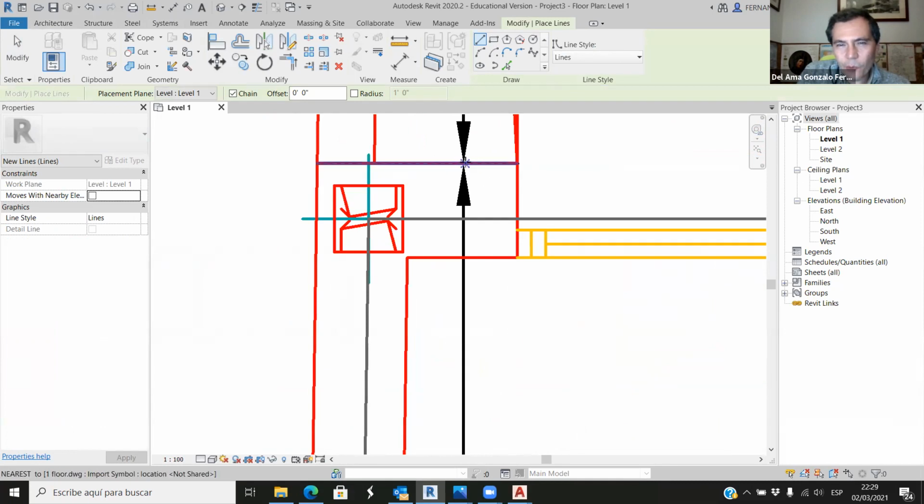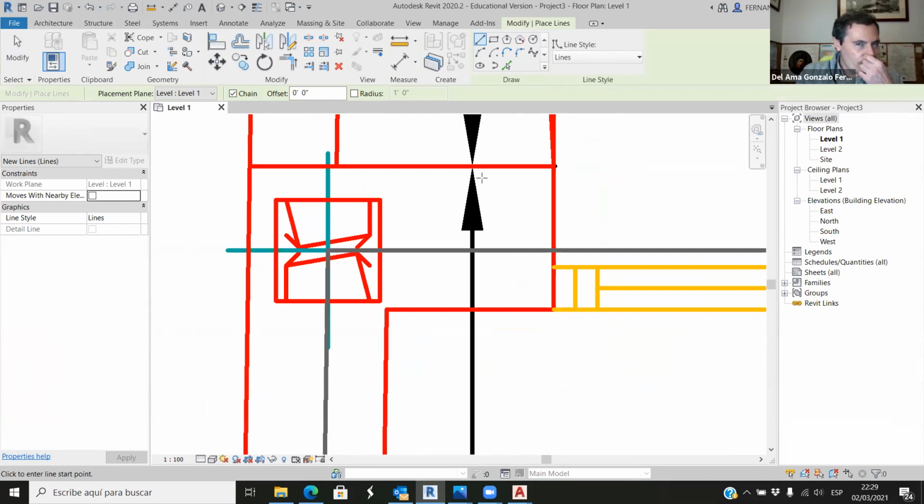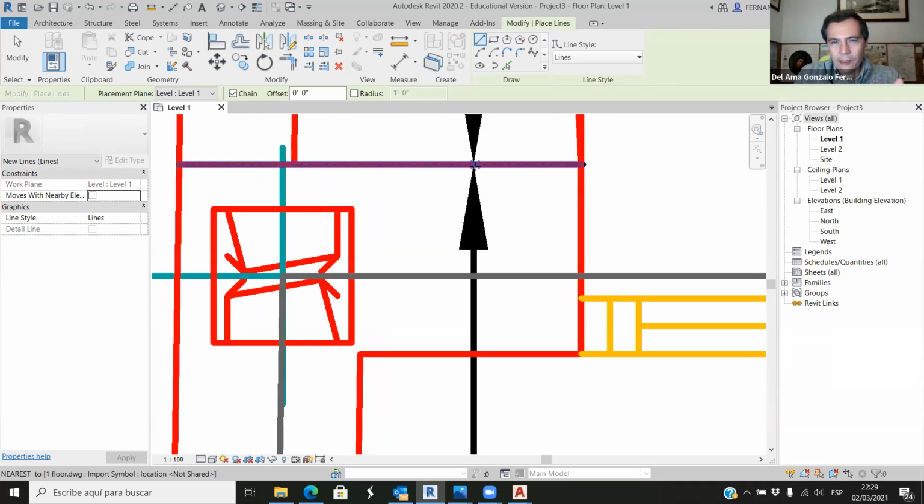As you can see, if you import a CAD file, if you import a PDF, last day I remember that we imported like a PDF file and you can't select things, but a CAD file, AutoCAD is an Autodesk software, so it's the same family. So it works well with Revit, okay? So importing things from AutoCAD to Revit, it's something that works well and it's accurate.